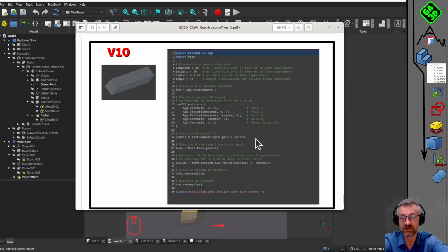Refine your solid by removing faces, which can make sense in certain situations. You can also do it using a sub-shape binder, which can be converted into a volume. Finally, you can create a macro that will also generate the same part.